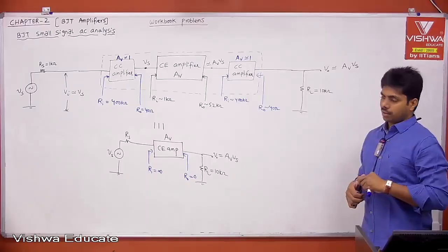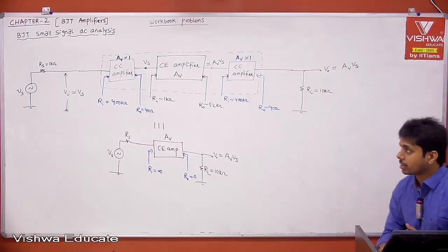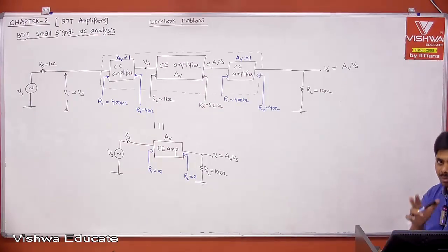That's why if you take your op amp slowly, you'll understand. Now if you open the op amp block diagram, you will understand the first stage and the last stage of your op amp, because we need input impedance infinity and output impedance 0 for a voltage amplifier. That we can get by using the CC amplifier. Very easy. That's why the op amp input circuit and output circuit are from CC amplifiers only. Okay. But I need to add one more thing before we correlate with respect to the op amp.